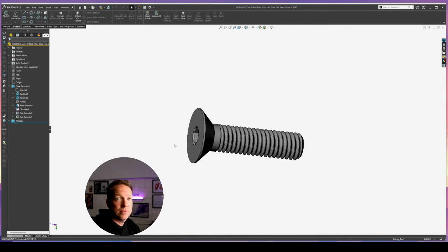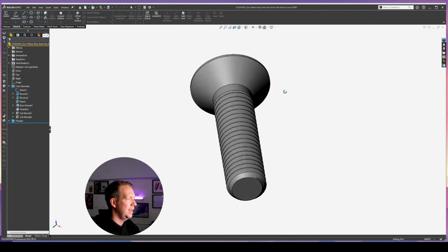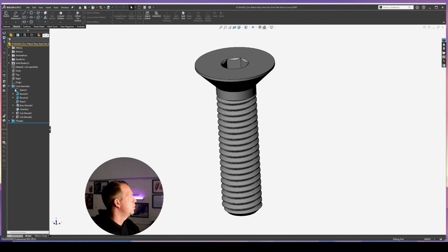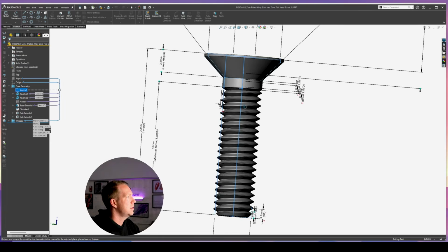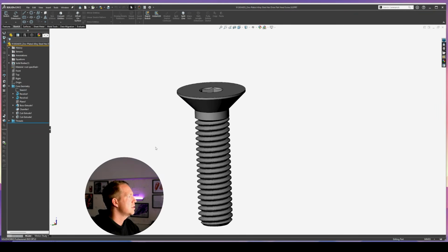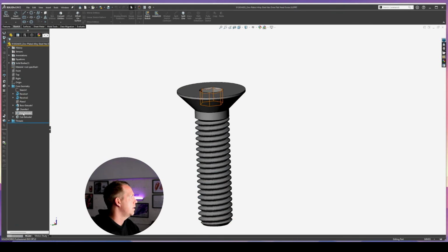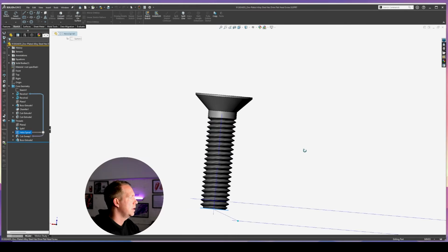And one of the things I think is best for a designer or engineer learning SolidWorks to use this library is to see how these parts are made. All right, these are geometrically accurate. The processes used to create these and the threads is accurate. An M5 bolt here is going to have a 0.8 pitch for the thread. And you can see that's controlled here with a helix.